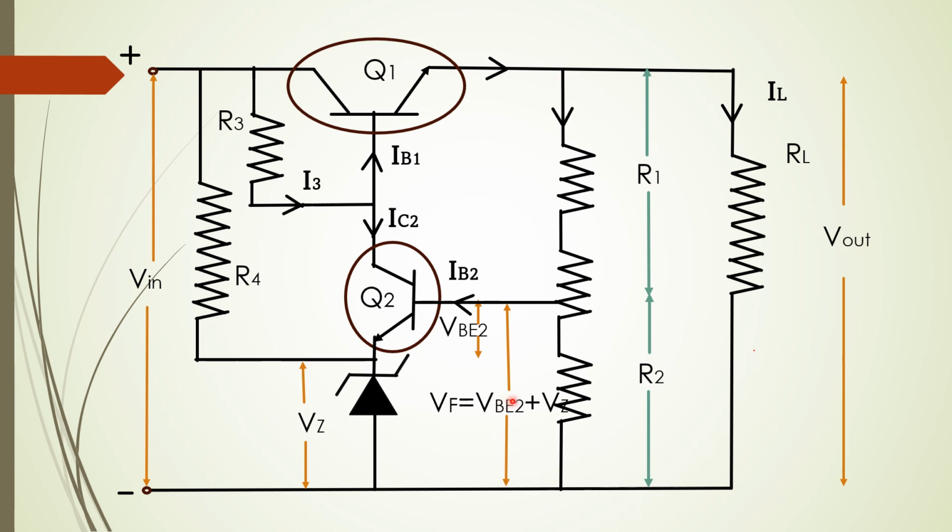Though it has proper control, there are a few drawbacks in the circuit. Excessive power dissipation happens, and due to the high power dissipation, the output of the power supply is limited to 30 to 40 volts, as a safe value of VC is 50 volts. Most importantly, there is no protection in the circuit, which means there is no overvoltage, overload or short circuit protection available, for which we have to provide extra elements and compensate for it. Thank you.